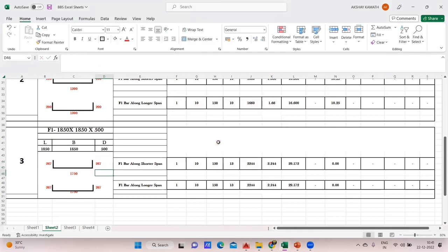Okay, it's not coming. Now it's okay. Now it's correct. See, it's coming to 67. Earlier it was coming to 66 point something. So now it is 267. Getting my point? What I did is round up here. When you do round up and put a comma and say 0, it will take the next higher value. Because practically 266.67 is not possible on the site. Okay, fine.